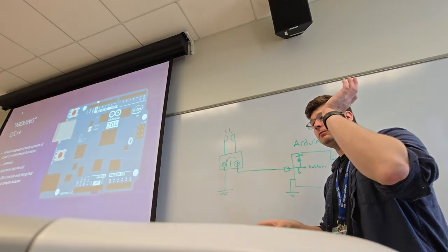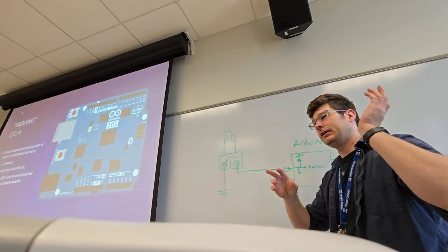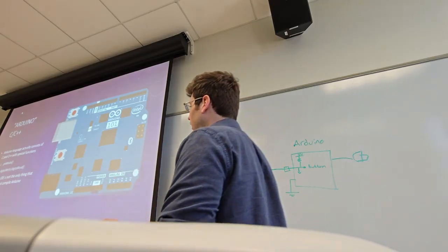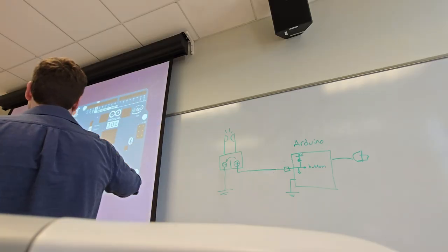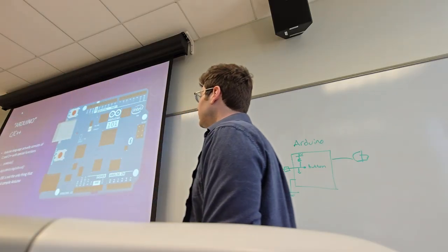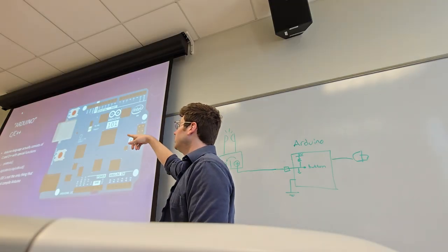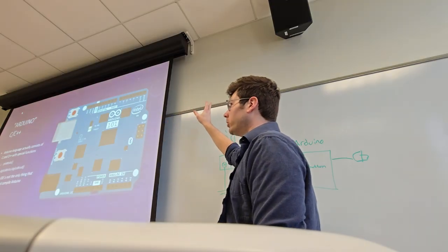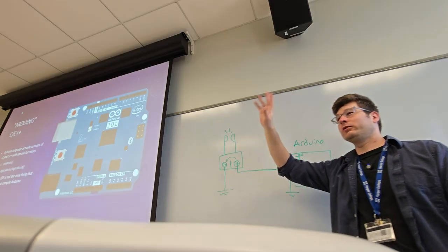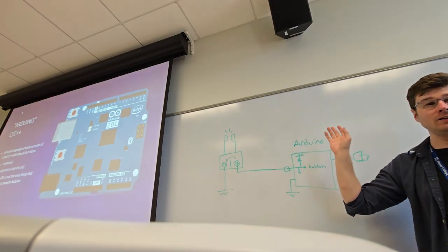There are bits that get set on and off to coordinate the configuration of certain pins. The way that pins are addressed is a little weird. For example, it's not 0 through 13. There are 3 or 4 different ports, and certain pins are on certain ports, and you just have to remember what they are.